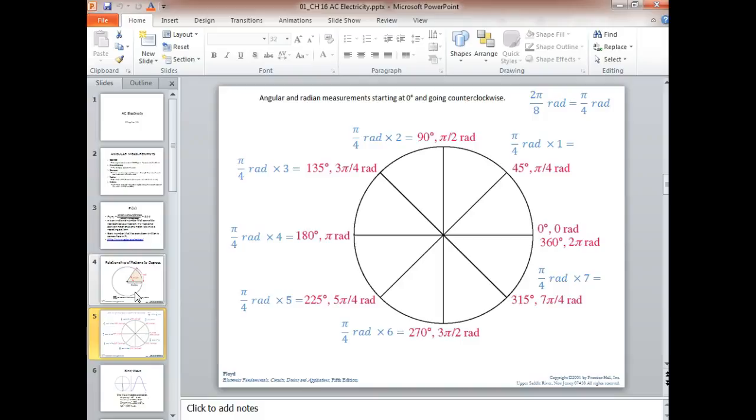Or you'll find out when you try to download it. Now that's one of the things you're doing when you select the processor. So when you bring up RSLogix 500, the actual program, and you bring up a new program, what's the first thing it wants you to do? Select the processor that you're using. And what do you think that's doing? Well, that's loading in all the instructions and everything that processor supports.